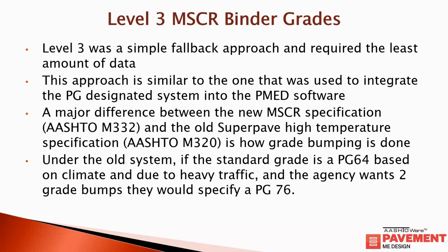In truth, the pavement will never see this amount of high temperature. It was just an artificial way of recovering a stiffer binder by testing the binder at a higher temperature. When using modified binder, this can provide some misleading information because many polymer systems often get softer very quickly at high temperature. Next slide, please.